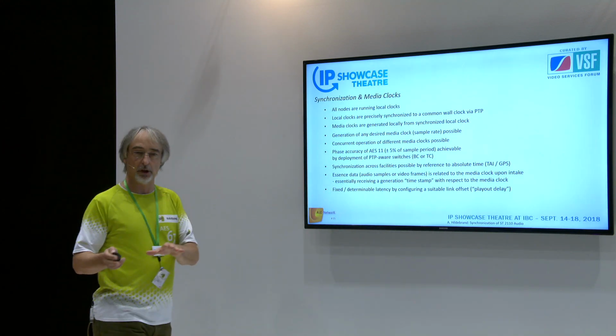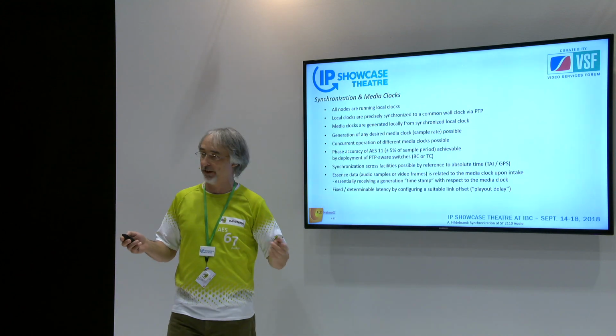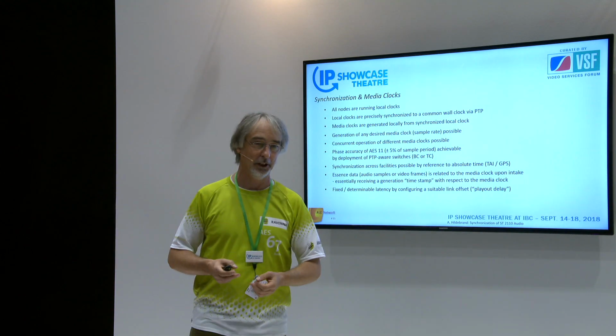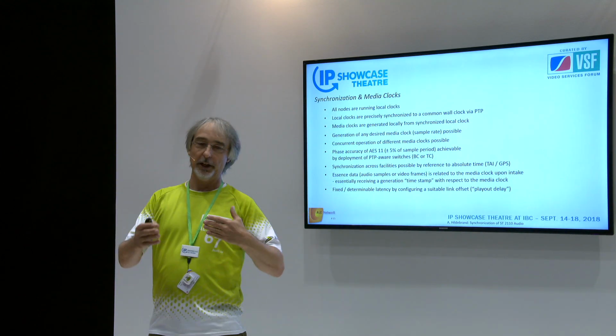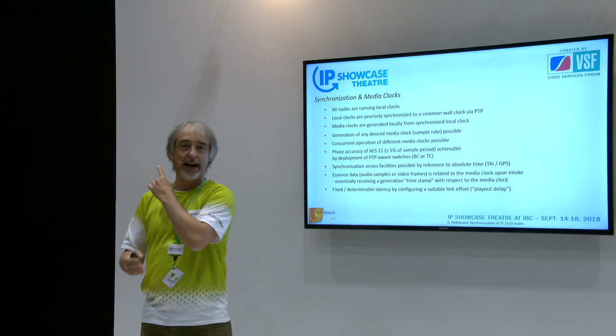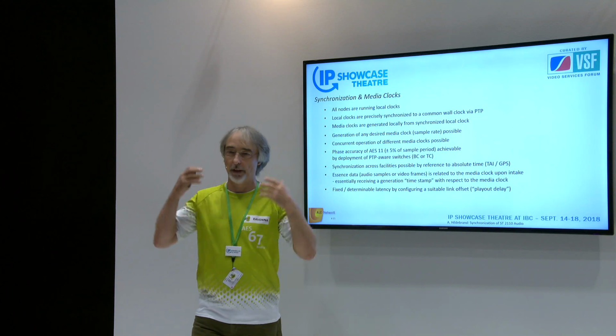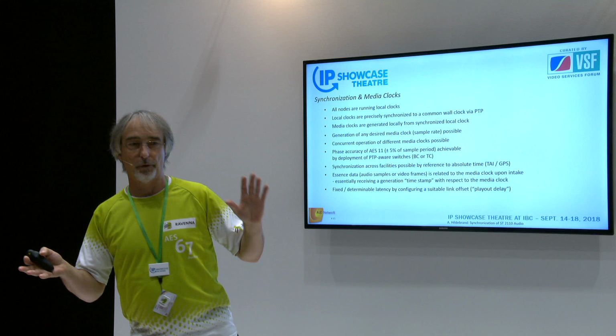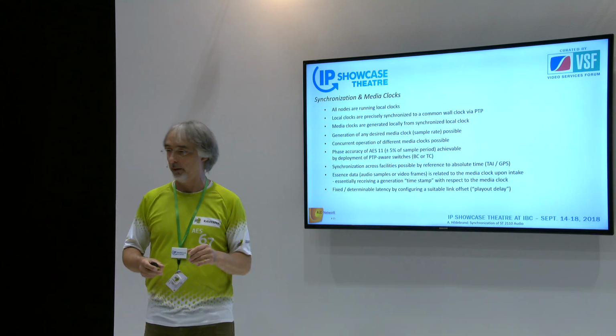Basically, that can be set individually for any stream. I'll give an example. For example, we have a front of house man, a singer, a performer, whatever. He needs in-ear monitoring. So we have the microphone. We want to have a relatively short packet time and feed that particular stream back on the shortest possible way so that the overall end-to-end latency stays, let's say, below 2 or 3 milliseconds. That is acceptable by most people.